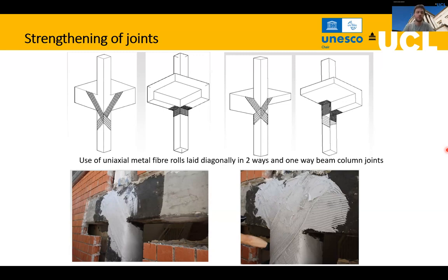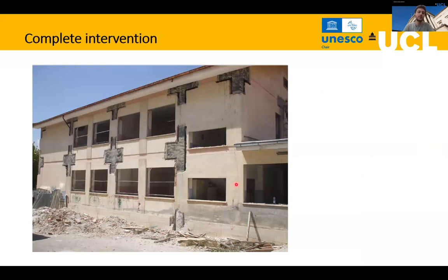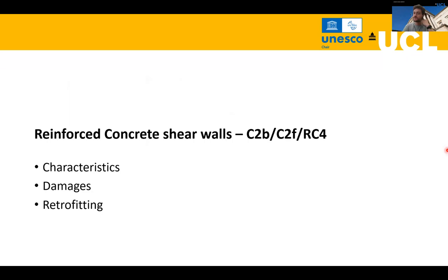So this is usually a problem because it is very difficult to retrofit them, but these elements are very important in a building. So you can see that in some cases you can cut the masonry over here, as you can see, and install an FRP jacketing in the elements. But this, of course, is very complicated to do, even though it is possible.